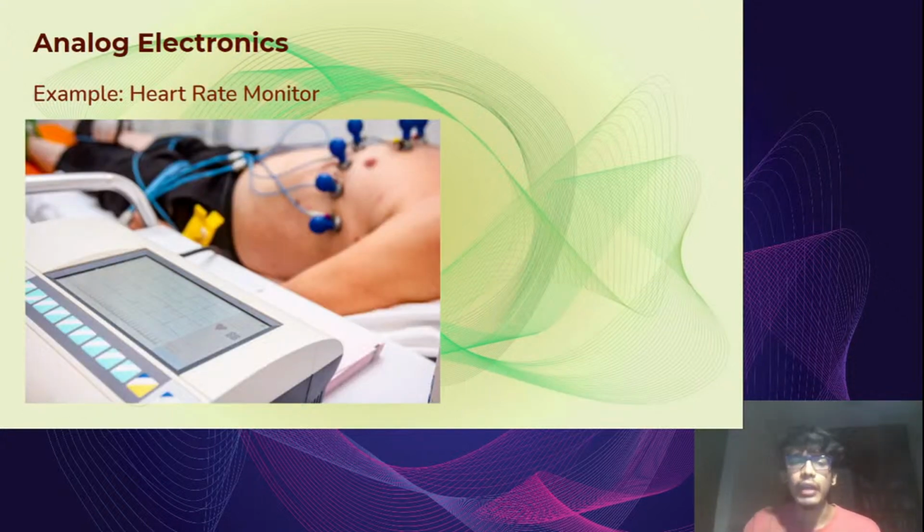Now, I'd like to take the heart rate monitor as a kind of case study for analog electronics. How the heart rate monitor works is that it has several conductive pads placed on your body which measure the resistance. As your heart pumps blood, the resistance changes ever so slightly. This change in resistance is then converted into a change in voltage by using Ohm's law, V equals IR, and it's amplified probably using an operational amplifier.